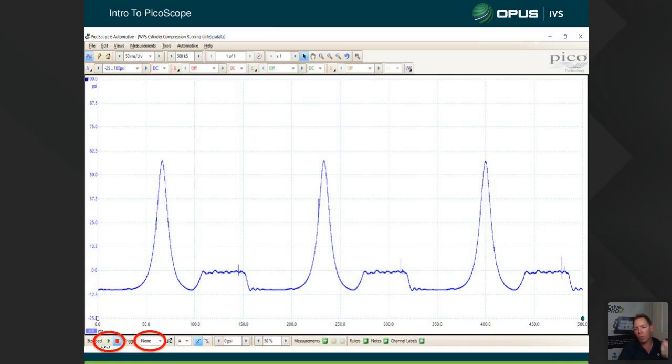And I'll be sitting there and probing, going, why isn't this working? And it's because I haven't come back down here and hit the record or begin capture button. So keep an eye on those two. The other thing it allows us to do is to capture a waveform. We can be looking at the waveform. We can just hit stop, and then we can let go of whatever we're doing and then come over and analyze the waveform on the screen. So that's very handy as well.